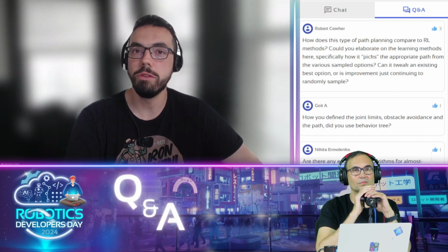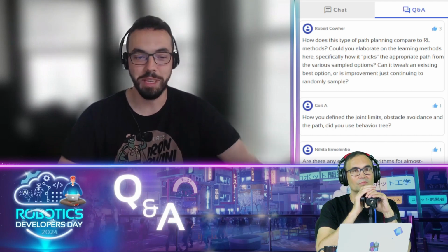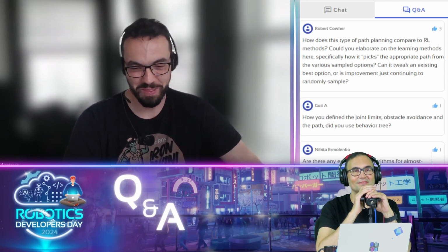With machine learning methods, they can do very impressive things, but you need to similarly find a way to validate them, right? There's been lots of ways to use RL to accelerate planning in lots of different ways. I recently saw some work that I think is a really good use. They try to use machine learning to do faster collision checking, by having a learned model generate these signed distance fields for collision. So you don't have to do these expensive polygon mesh collision pairs. You just trust that your learning algorithm does stuff right. It comes with risks, right?